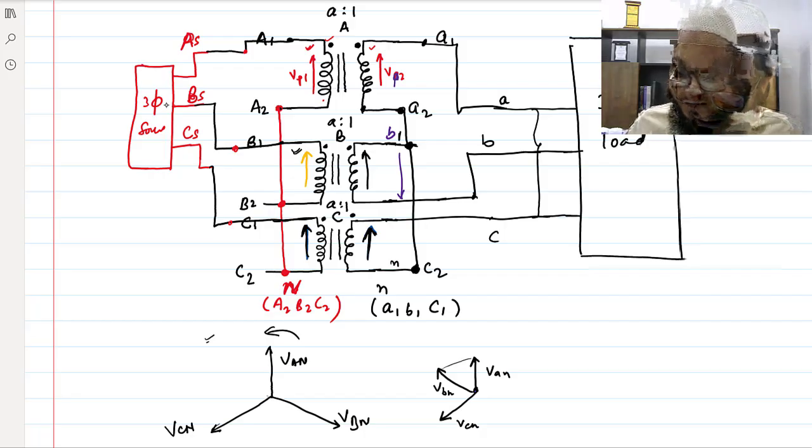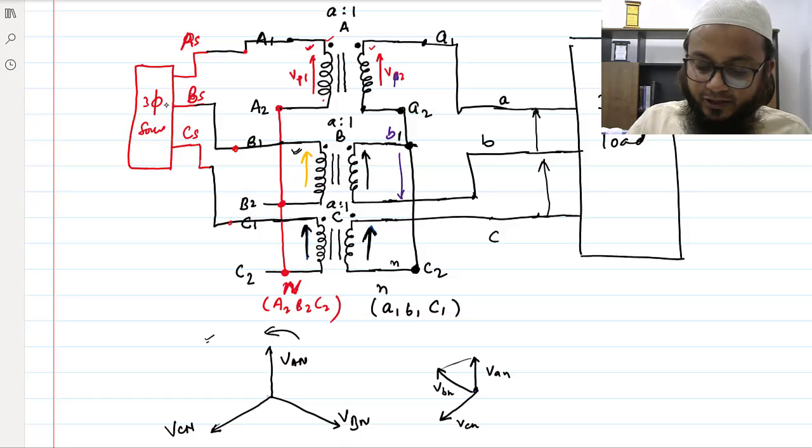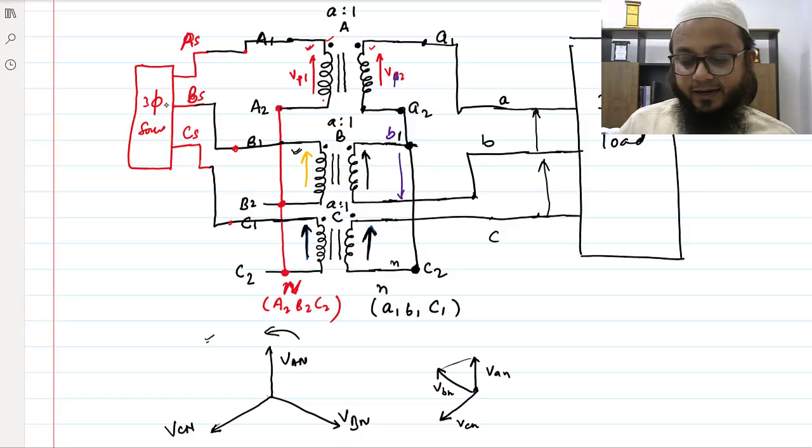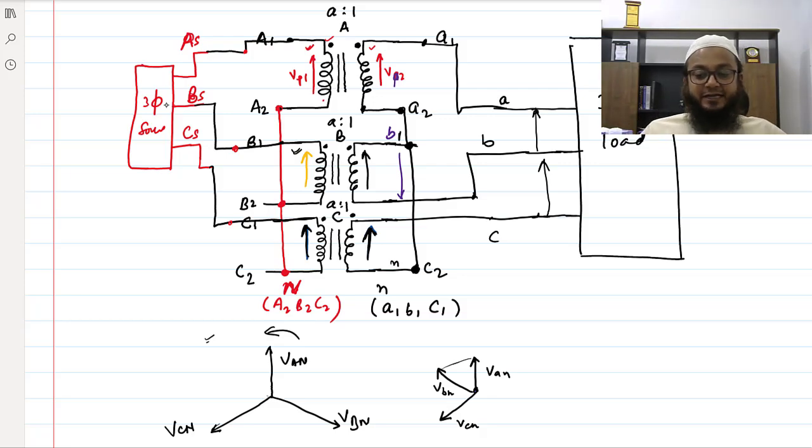AB will have only this much difference, right? And even line BC, AB will have different voltage, AB and BC. So you'll get an unbalanced supply at the load, at the line voltages here. Though the phase voltages are balanced, the magnitudes are balanced, okay. So if you measure individual phase voltages, you will say, okay, no problem is there. But if you measure the line voltages here, the line voltage would be different. Since this was a star connected one, there is not so much of a problem.